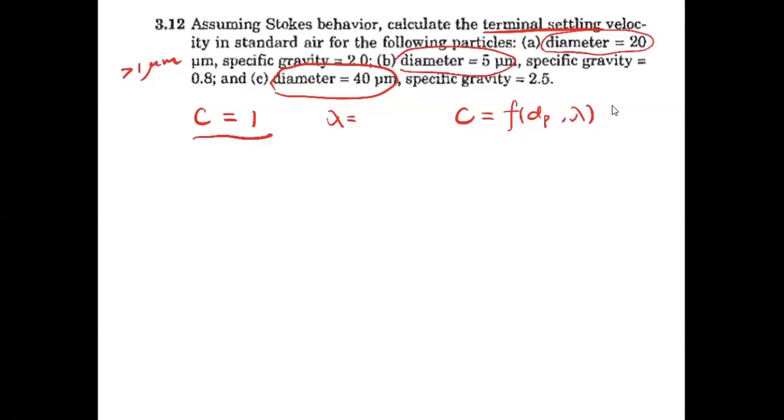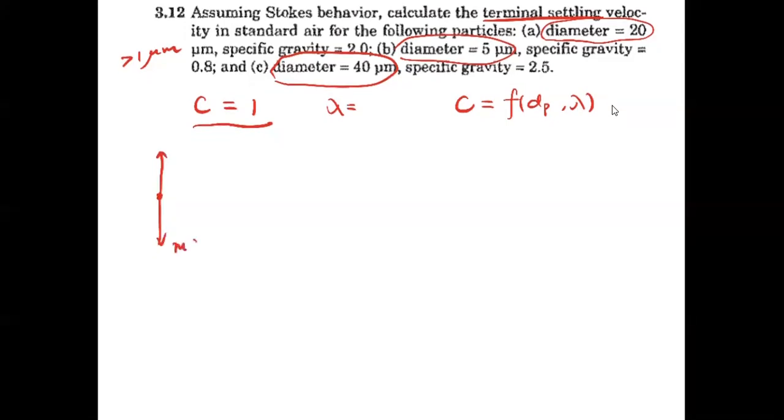So here again, I will derive the equation for the settling velocity. Basically we equate the gravity with the drag force. So we put in gravity equal to 3 pi mu dp. Originally we have to divide by c, but here, because the particle size is larger than 1 micron, we can assume that c is equal to 1. And finally, we have the VR, which is the relative velocity of the particles.